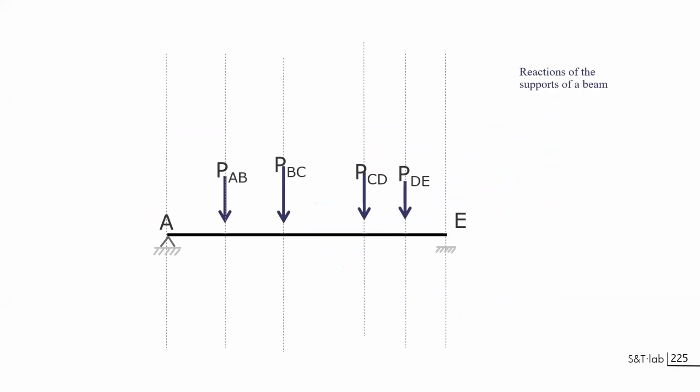So first we have to establish the way to solve it algebraically, and then show the corresponding approach with graphic statics. You have here a series of forces that will be applied to a beam. There is a missing support, a sliding support on the right, supporting forces. This disappeared, I'm sorry for this. And if you want to make the equilibrium, you know that you have three components of forces, one vertical, one horizontal, and one vertical here. And you have three possibilities of movement, as we have seen: translation horizontally, vertically, and rotation.